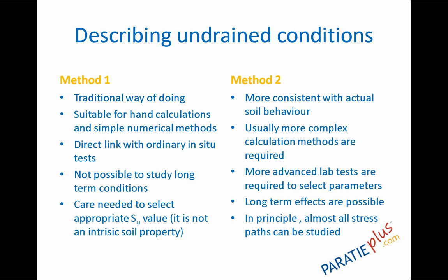And there is, in my opinion, also another merit of this method: it is quite, I don't want to say simple, but quite ordinary to determine the undrained shear strength capacity by means of in situ testing like CPT testing or NSPT testing, along with some very familiar and well established correlations.